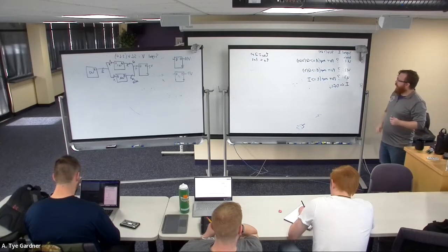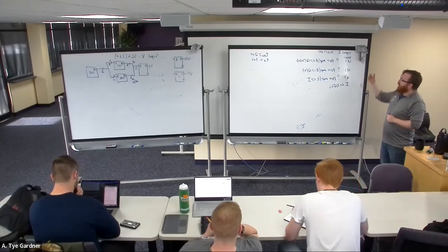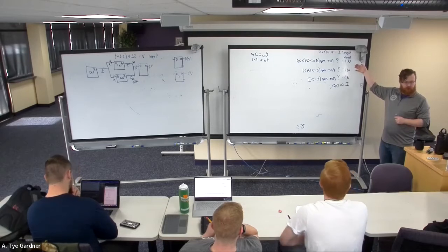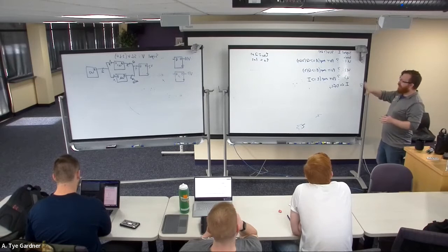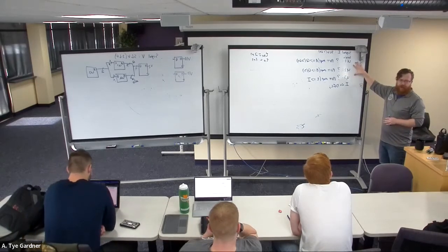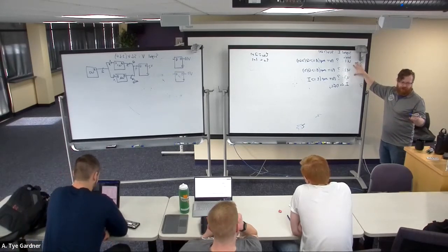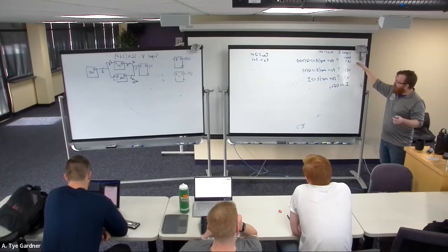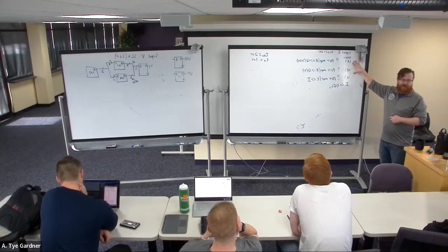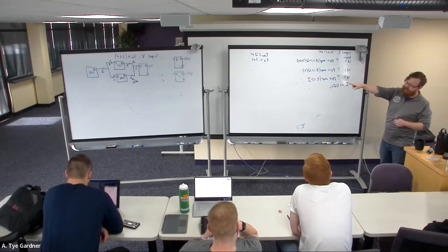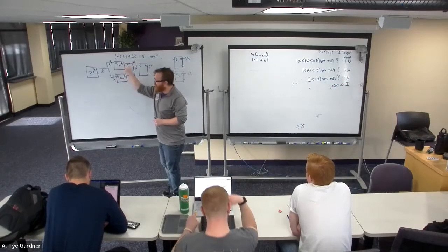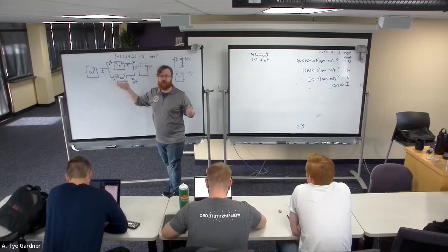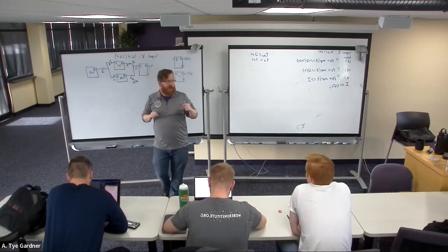The next question that kept coming up around the same thing is this structural code, right? There are 2 options in this, structural or behavioral. When you create a new design file, it defaults to calling it behavioral, but that's just the name of the architecture. It doesn't actually mean it has to be behavioral. Structural is just a description of how things are connected together. That's what these block diagrams are really good at conveying: how are these devices connected together? That's structural code.